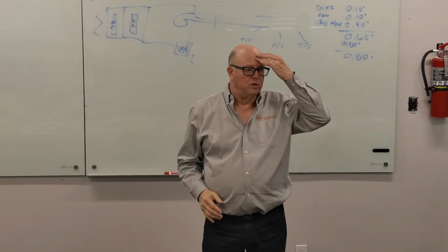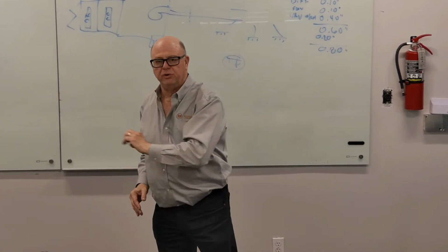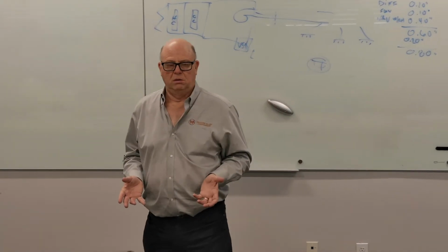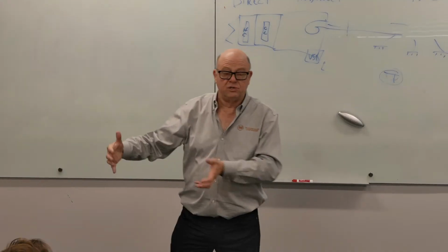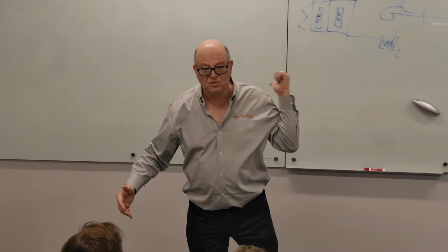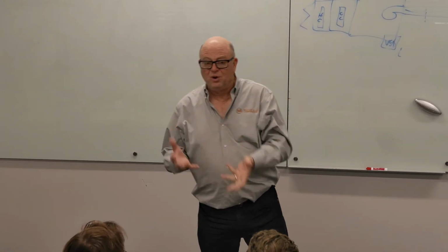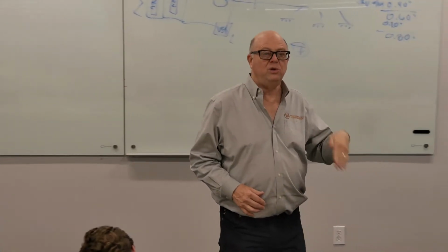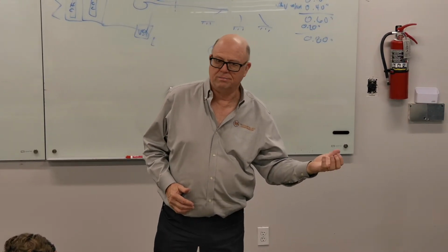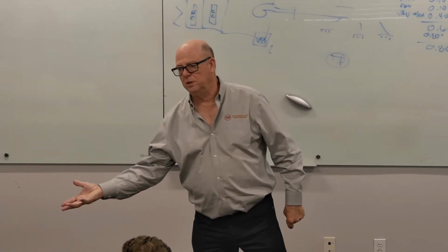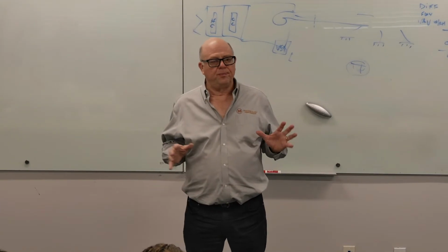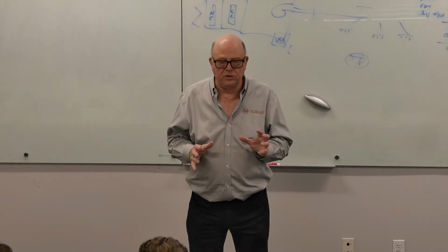And that's counterintuitive, because when you talk to building engineers, they're going to think, well, making colder air costs me more money. Well, it does cost them more refrigeration. But this is variable volume. If we're making the air colder, we're giving them less air. And you save more on the air, like 1.5 to 1. You save more on the air than you spend on the cooling. And so that is a wives' tale you're going to run into forever.